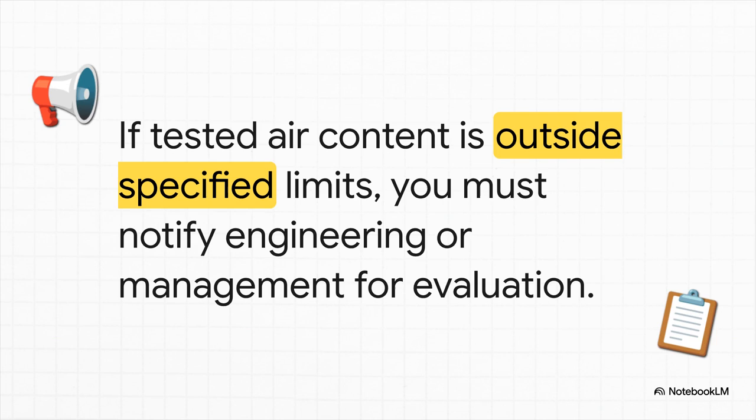Well, your job isn't to fix the mix on the fly. Nope. Your job is to be the reliable source of truth. You test the air content accurately, and if it's outside the specified limits, you report it immediately. You provide the correct data so the engineers can make the right call.